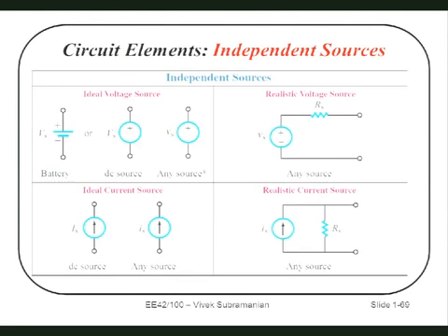If I gave you a battery that's just a voltage source, let's say it's a 10-volt battery, and I put a 1-ohm resistor across it, how much current should flow? 10 amps. Okay. If I put a 0.1-ohm resistor across it, how much current should flow? 100 amps. In theory, I could keep going.